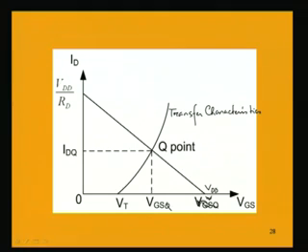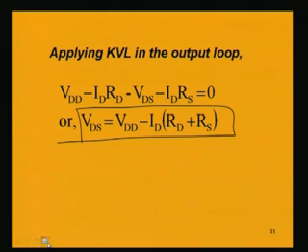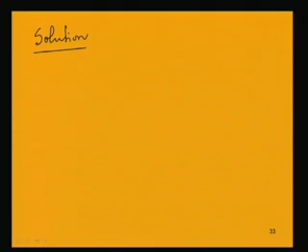So, that has to be found out in this problem. We will be finding out basically the transfer characteristic and the straight line, and where they intersect, that point is the operating point. The operating point will give you the voltage and current values under DC.